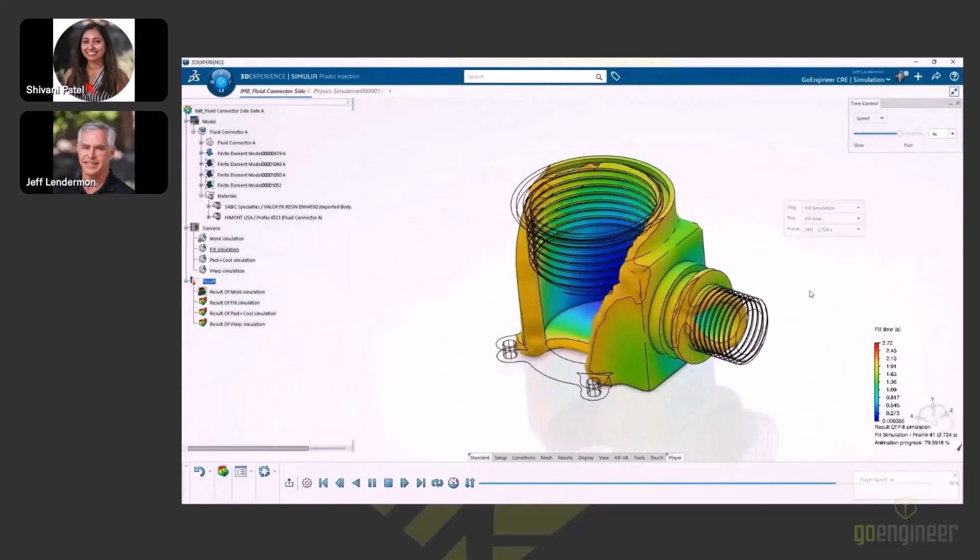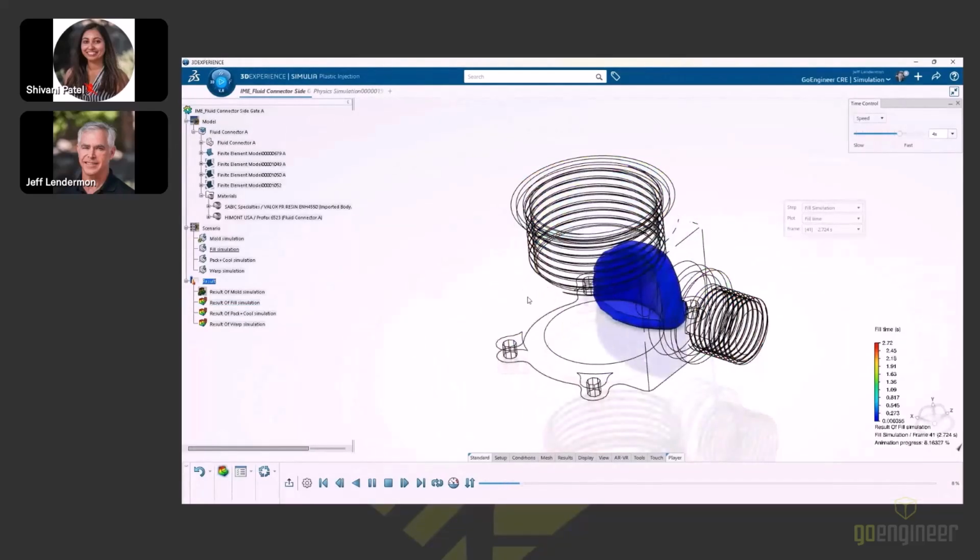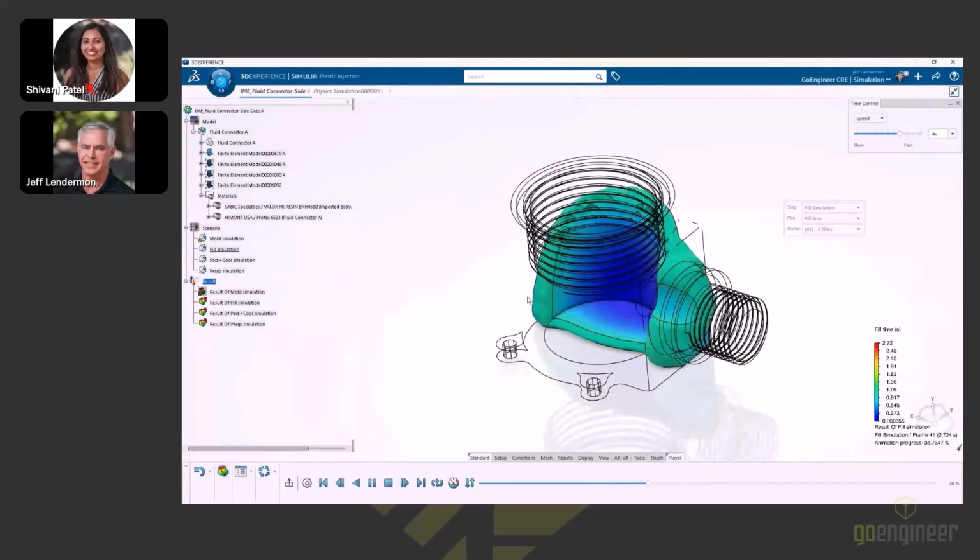And we can see it's creating this weld line. So different areas, if it zips up like a zipper, it's usually not too awful, but when you have an area that just butts straight head to head on each other, then we start looking at problems.